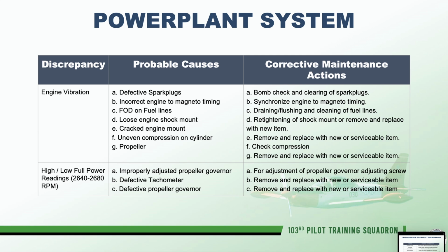For example, if you encounter engine vibration, don't just jump to conclusions. The probable causes can vary widely, from something as simple as defective spark plugs to more complex issues like propeller damage or even internal engine problems such as uneven cylinder compression. The corrective actions are equally diverse.